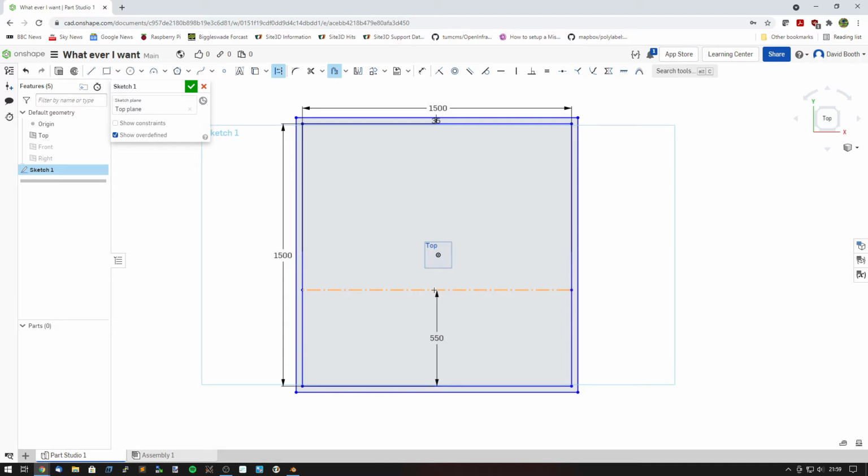So that's the center of that line where the golf balls are going to go on. The next thing I want to do is put an offset from this line up by 200mm, which is where the stop line is going to be. So I'm still in those commands. I can just select that one again, change the direction, left click, and again that's going to be 200mm. And that'll put that clearly in the dead center of the box.